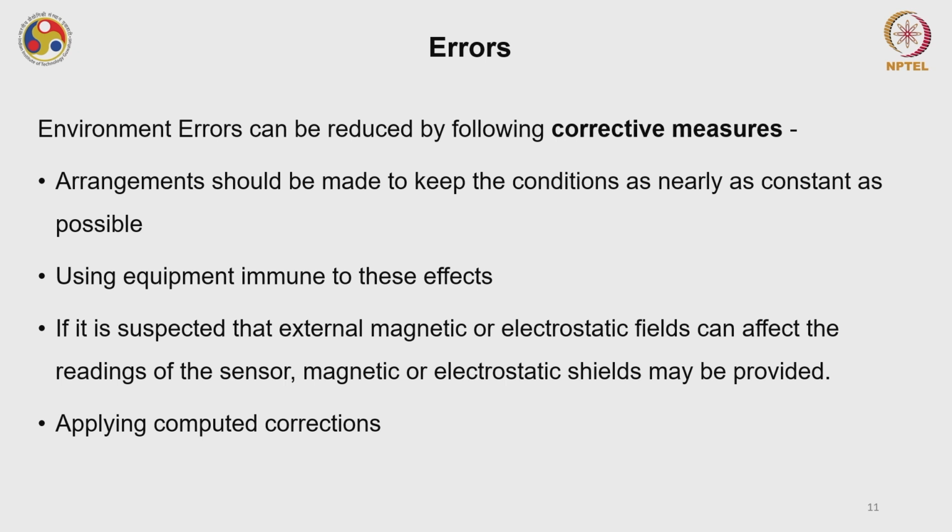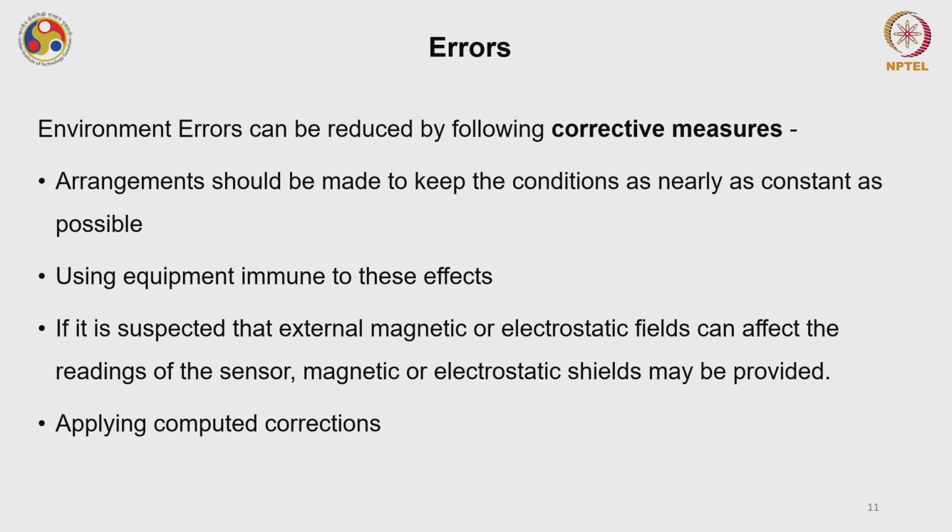For example, if I am developing a sensor in a clean room in IIT Guwahati, and I have tested it at, say, 50% RH at 25 degrees Celsius, and I have not checked it at 75% RH or 90% RH, or at different temperatures, and I do not take care of these things, and then I try to deploy this sensor in a very humid place near the seaside, my readings will be totally erroneous.